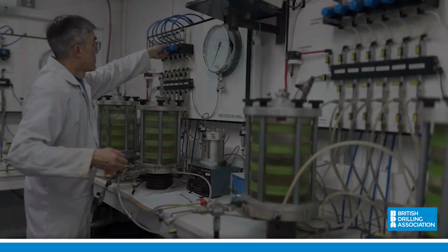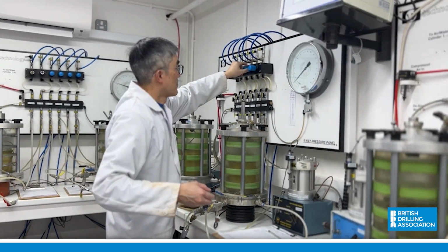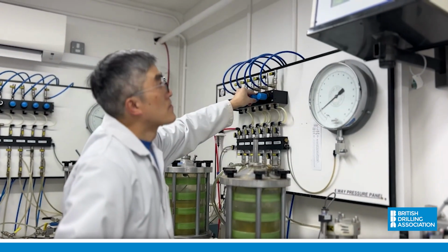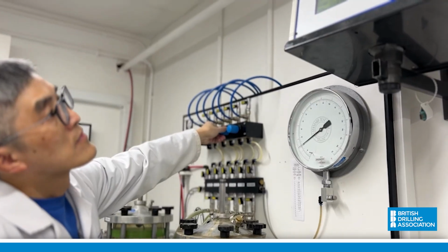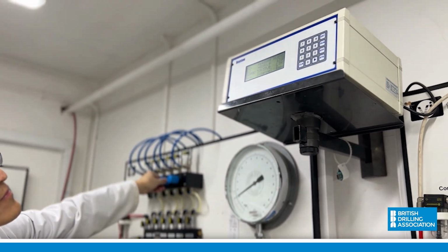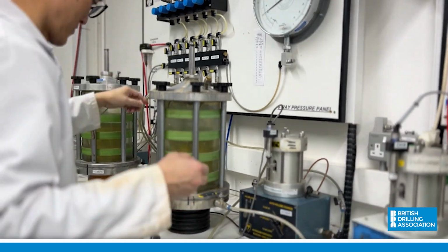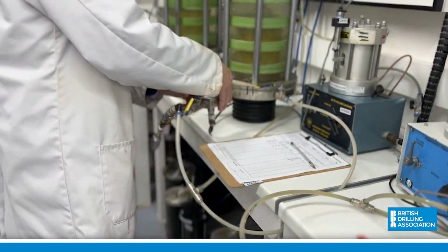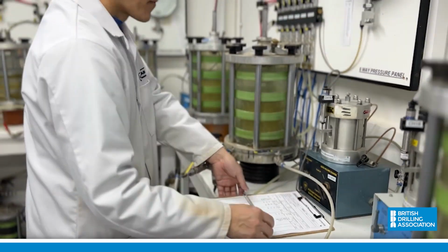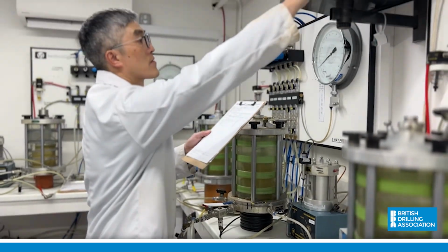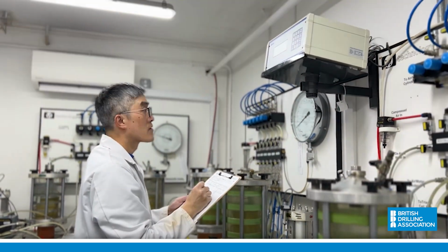With all of these tests, whether utilising disturbed or undisturbed samples, the representativeness and reliability of the results are totally reliant on the quality of the sample and how it has been looked after up until it is tested. If a sample has not been cared for correctly, the results of its testing cannot be reliably called upon for engineering design.